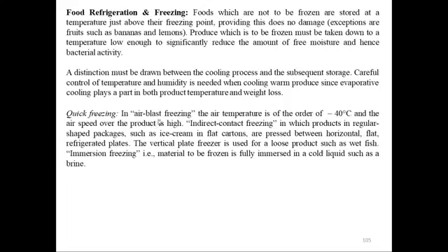Quick freezing. In air blast freezing, the air temperature is of the order of minus 40 degrees centigrade and the air speed over the product is high. Indirect contact freezing, in which product in rectangular packages such as ice cream in flat cartons are pressed between horizontal flat refrigerated plates.